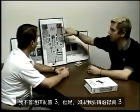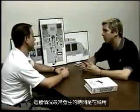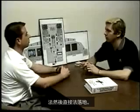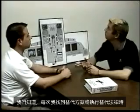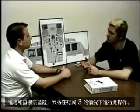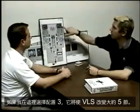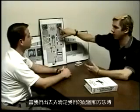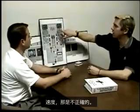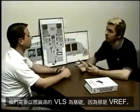I do not select config 3, however, if I'm going to land flaps 3 for an ECAM driven situation. The most frequently occurring time this would happen would be during an alternate law and then direct law landing. Alternate law approach, direct law landing. We know that every time I do an alternate law approach and a direct law landing, I'm going to be doing this in flaps 3. If I were to select config 3 here, it would change VLS by approximately 5 knots. And when we go out and figure out our configuration and our approach speeds, that'd be incorrect. We need to base this off of VLS for flaps full because that's VREF.